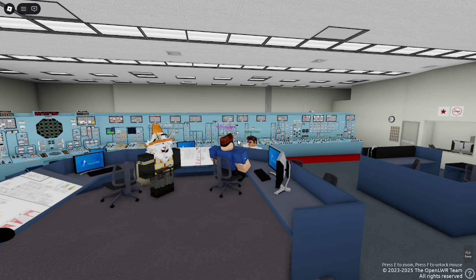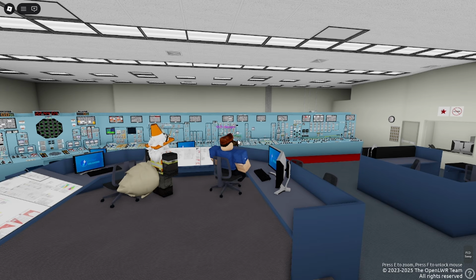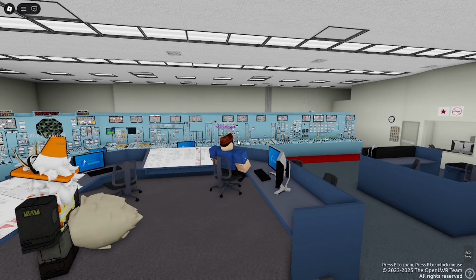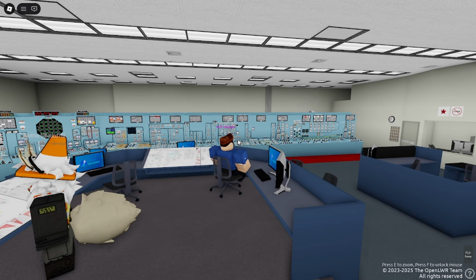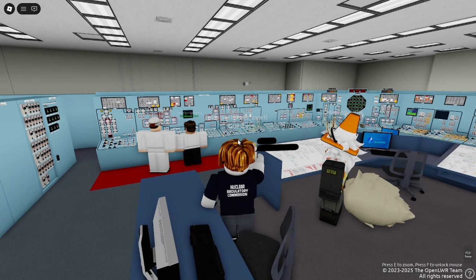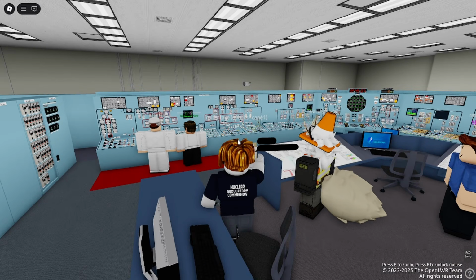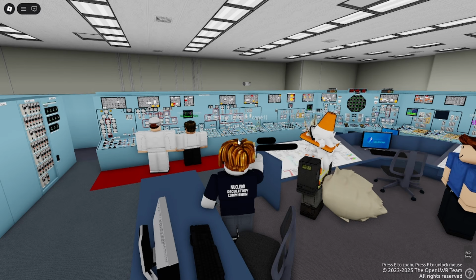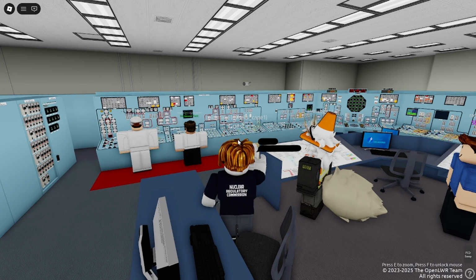Drywell pressure. Stand by on that. Dingo, yes. Could you open the RHR shutdown cooling isolation valves now? Open RHR shutdown cooling isolation valves. That's correct. Drywell pressure is minus 0.01 pounds stable. Incorrect, that is minus 0.01 pounds stable. I understand it's minus 0.01 pounds stable. That's correct.